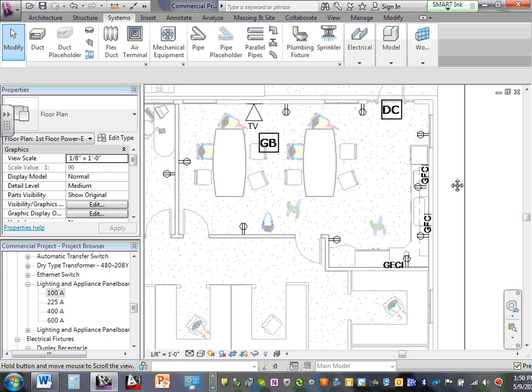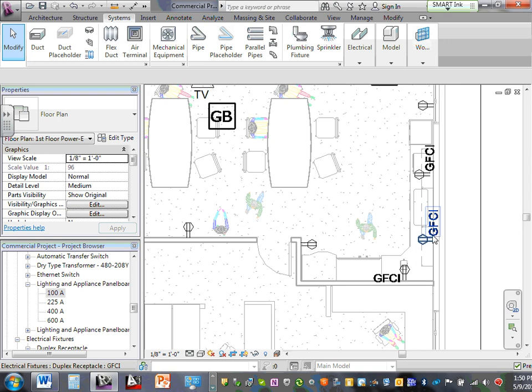Now, how do you circuit and how many receptacles on each circuit? Typically, guys, in a commercial industrial building, 4 to 6 receptacles, we throw a circuit for them, unless they're dedicated to equipment. If there's a certain equipment, a bigger printer sitting there that needs power for itself, we give it a dedicated circuit. We're so generous when it comes to the commercial layout.